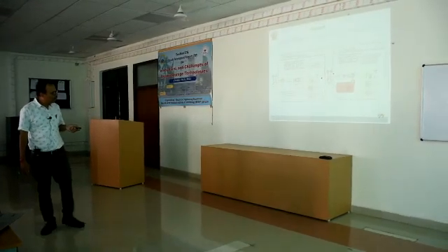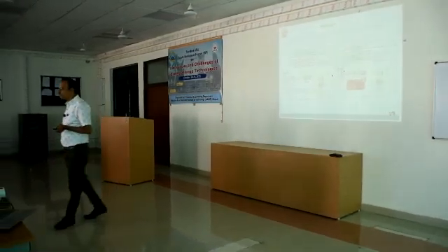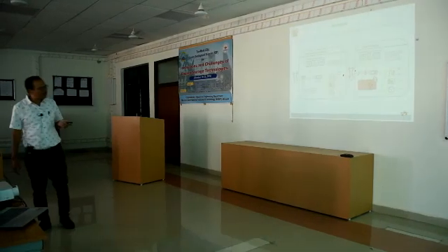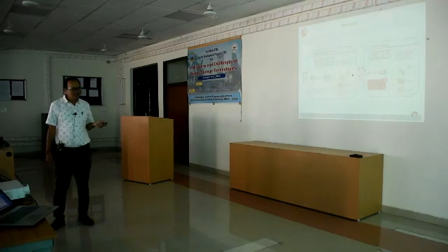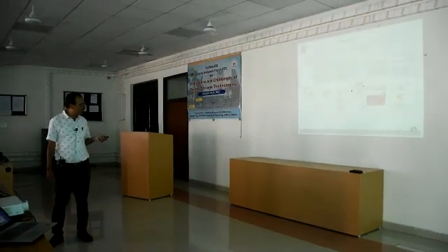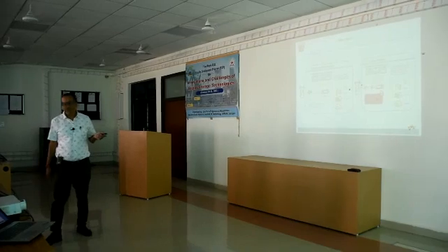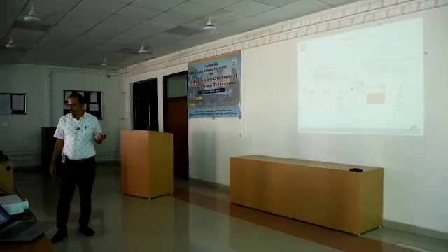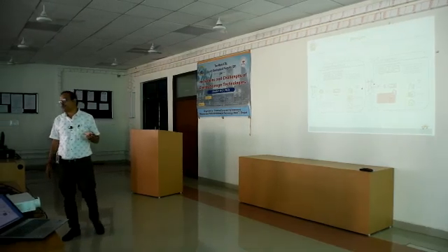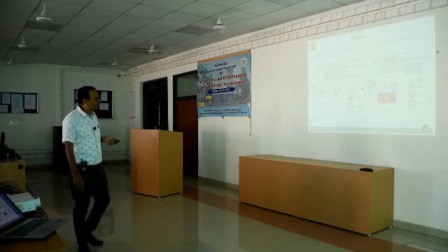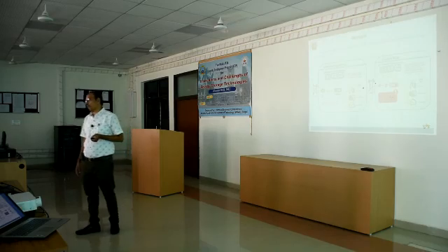Okay, and you have a user, maybe industry, maybe a residential building, maybe a commercial building. So when you are connected with the grid, the flow of power may be bidirectional. Sometimes the power may flow in this direction, and sometimes it will flow in this direction. It depends on what is our need and what is the local generation available to us. When generation is more, we'll feed the power to the grid, and when generation is less, we'll receive the power from the grid.